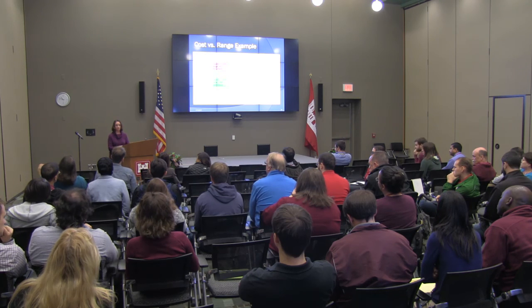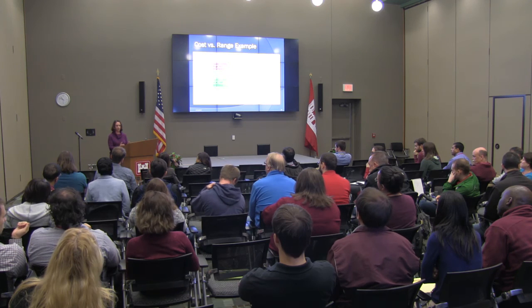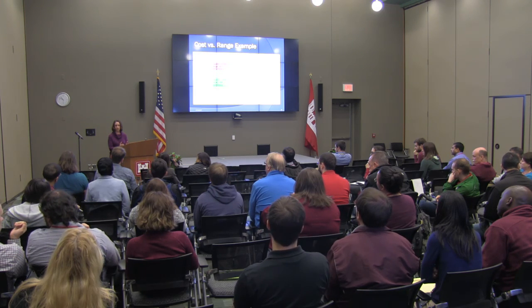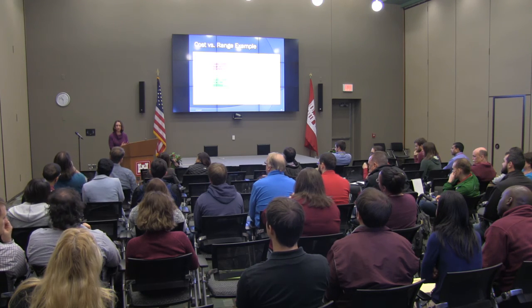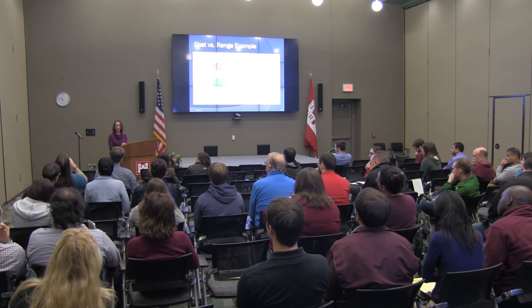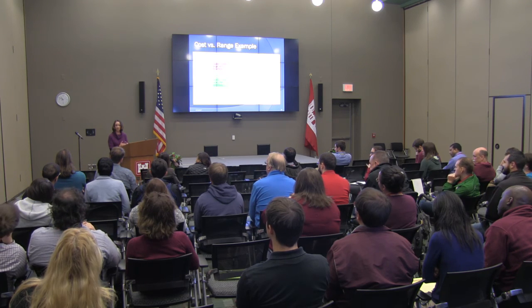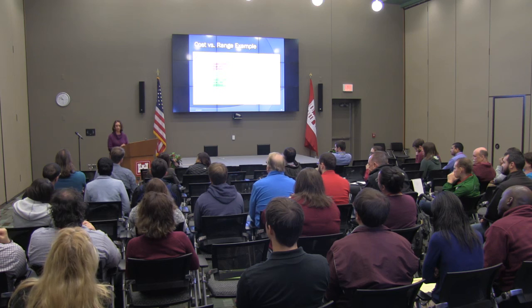So the full design space in this case for LCAAT was generated by the design team, a clean sheet design team. They came up with 9 design variables. On those 9 design variables, they ran a multi-objective genetic algorithm. And I want to say they went for like 900 generations. In those 900 generations, that produced the 270,000 set of designs based on those 5 objectives.